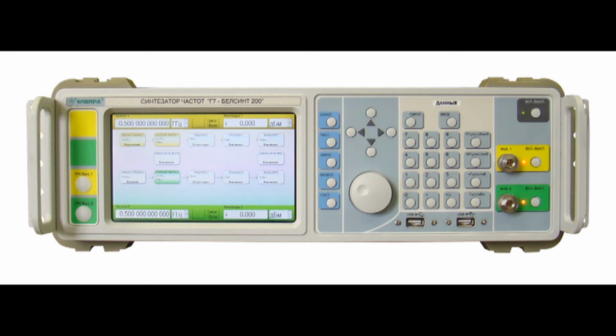This is an extremely good unit for any kind of two-tone dynamic range testing tasks, since its architecture built around quicksync synthesizers provides very low phase noise across the entire frequency range up to 20 GHz, and it provides two signals with an inherently good isolation which do not modulate each other, and this is an extremely important feature for any type of intermodulation distortion measurements.